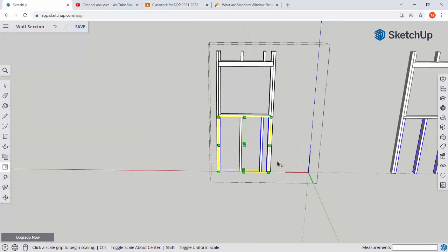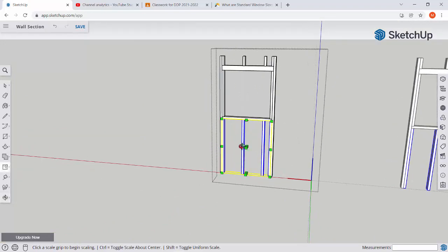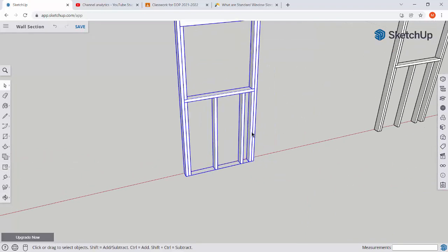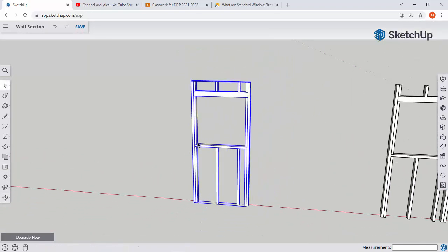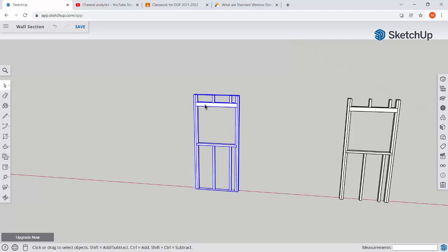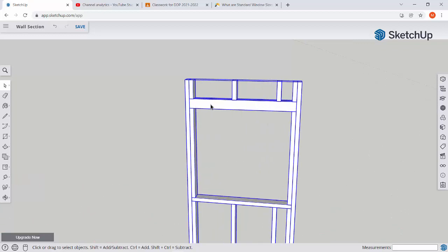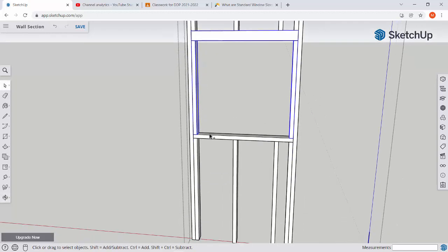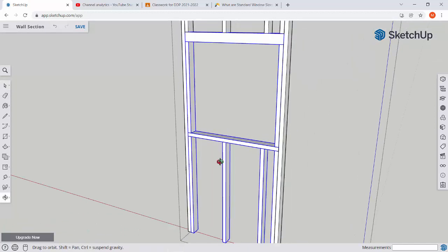So there we are. What do I have here, my friends? I have a framed out window. Wow. So right here's our window. And just like the door, this header is going to distribute the weight down to the jack studs, go through this sill plate directly down to the support underneath as well.